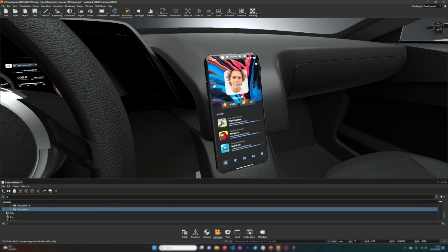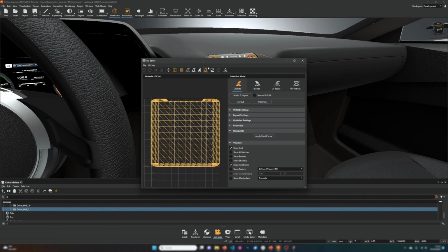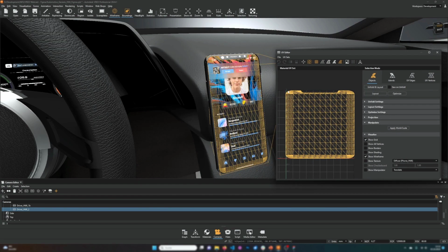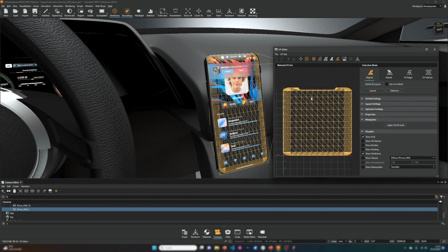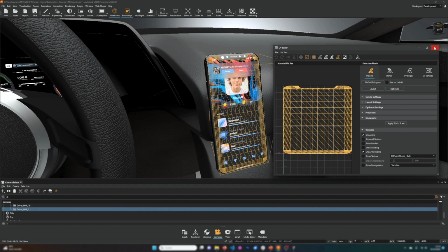The last step is you have to define proper UV maps for your geometry. So if I'm looking at this, the UV map is stretched onto the whole area of the UV map from 0 to 1, and then you can properly align your web engine texture to the geometry.